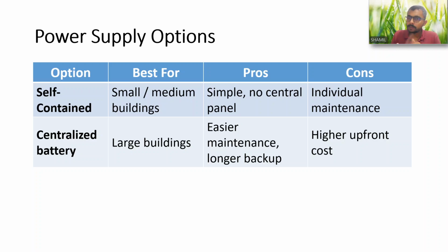The advantage of this one, the pro, is that it is simple and there is no central control panel. But the disadvantage is that you have to maintain each light fitting individually. That is the only disadvantage for the self-contained lights.